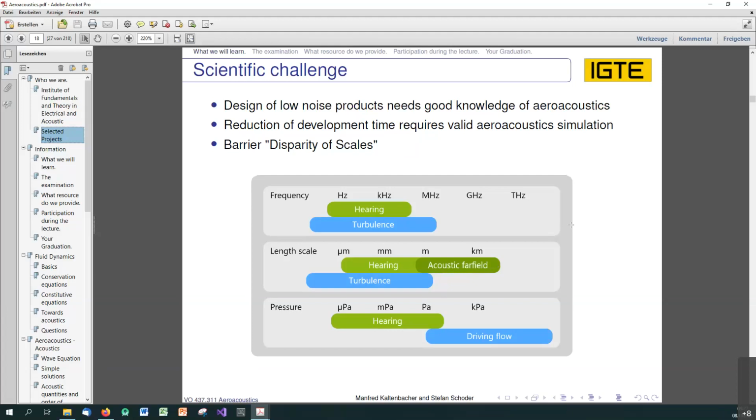Another question. Could we also differentiate in terms of velocities? So how flow velocity is related to acoustic velocity, or are there any relations? It's very similar to the pressure. Just imagine that the velocity squared is some representation of energy, then you have more or less a similar relation as the pressure relation.